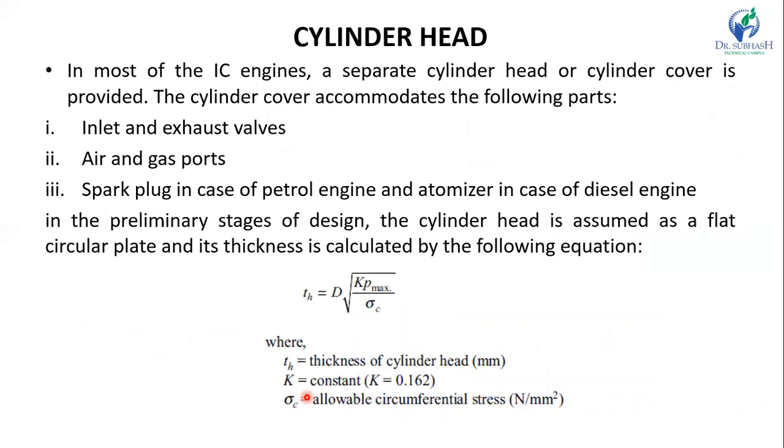Now let us design the cylinder head. In most IC engines, a separate cylinder head or cylinder cover is provided. The cylinder cover accommodates the inlet and exit valves, air and gas ports, and the spark plug in case of a petrol engine, and the atomizer in case of a diesel engine. So these parts are accommodated by the cylinder head.